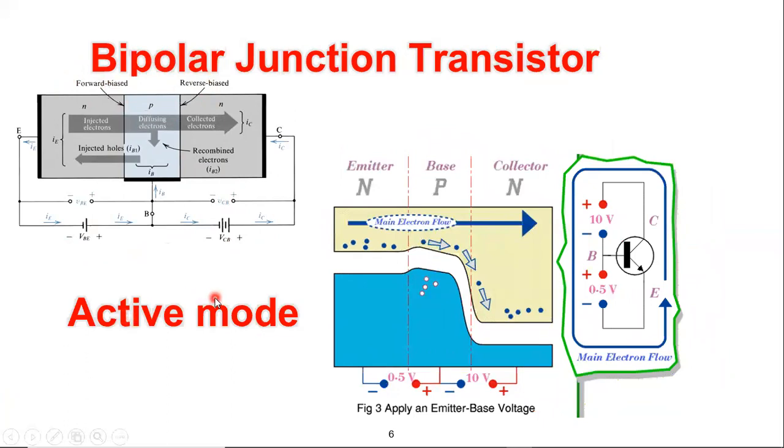Then, what about other conditions? You can simply say that this is two diodes. So we have basically four alternatives: forward-reverse, reverse-forward, forward-forward, and reverse-reverse. So we should have four regions of operation, and this is true. However, again, the active forward mode is the most interesting mode in BJTs. Let's now try to pass quickly over the other three modes of operation.